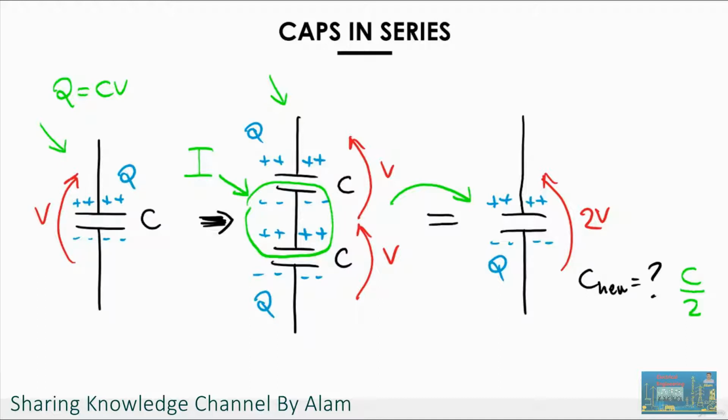So actually, when you put two capacitors in series, the effective equivalent capacitance is smaller than the initial capacitance, and we understood that by looking at this simple example where the charges on the middle plates that get connected to each other get simplified away. So for a higher voltage, you actually store a smaller amount of charge. So the equivalent capacitance becomes smaller.